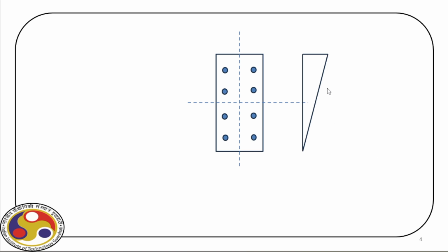Now, the moment we have XU lying outside, say this is the case, then we have to prove that maximum strain is 0.0035 minus 0.75 times epsilon minimum. So let us complete the diagram.